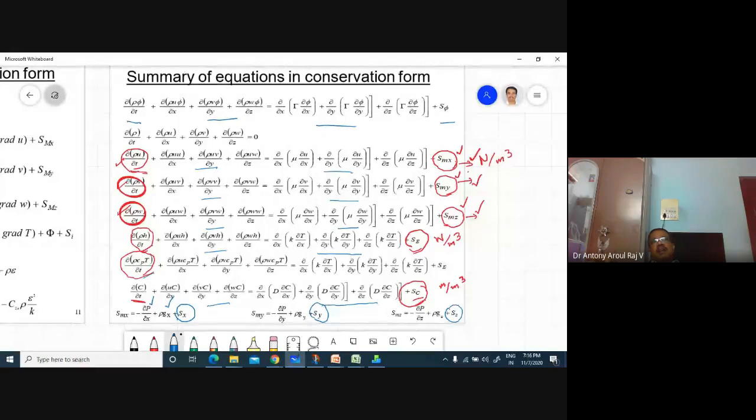Just you open the valve. What is happening? Outside you are having atmospheric pressure, inside you are having a high pressure. Because of the difference, flow is created. So that means the pressure difference can create a flow. It can help us as a source term for creating the flow, so that is this term. So if in a modeling zone you are having a pressure difference, depending on where you are having the predominant flow, you can have the X component of pressure, Y component of pressure, and the Z component of pressure. That is how the pressure can appear in the source term.